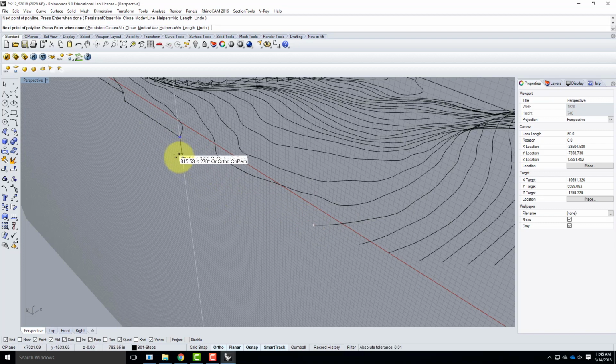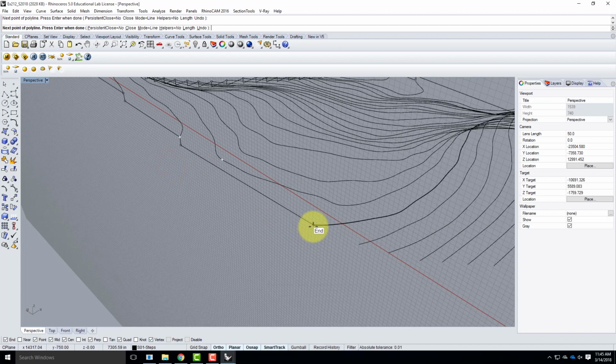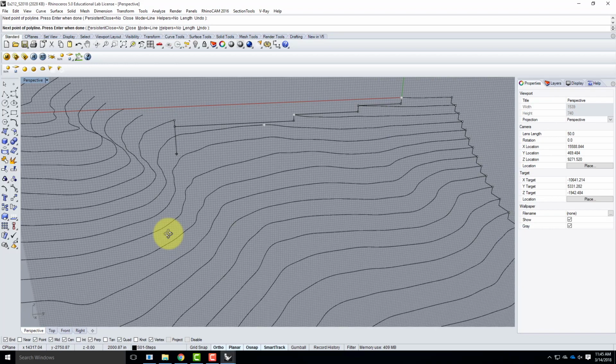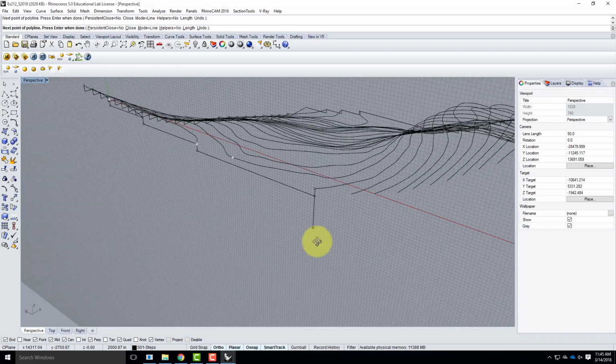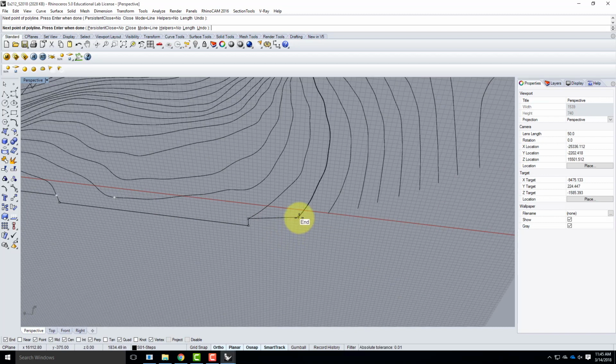So this, I actually have to go down, over, and then back up, because this is like a little valley in the hill. So I'll go 31.25 feet down. I'll go over till I meet that point right there, and then I'll come back up. So it's only when you reach where two contours are even across the side, in which case you're going down and then across. Now as I come over here, we can work my way back up. So there I am, working my way back up.